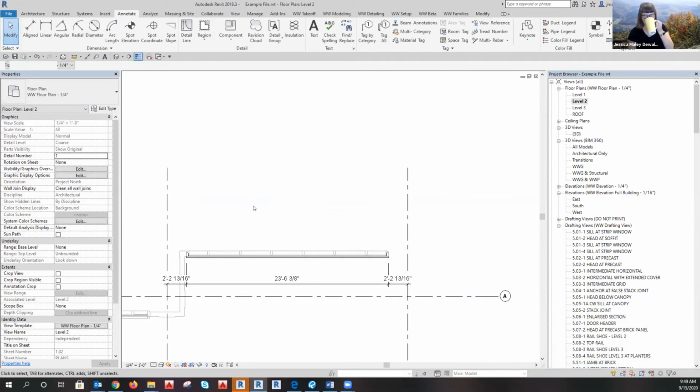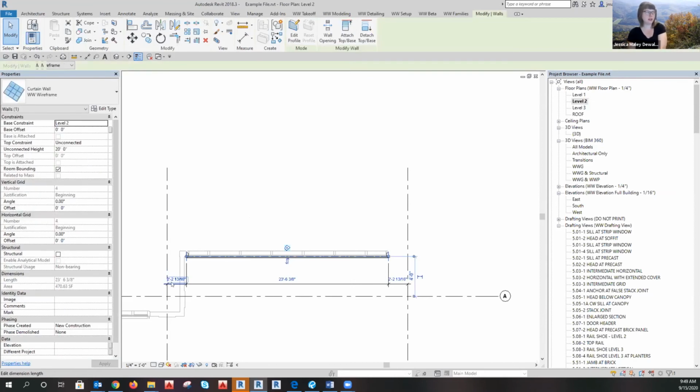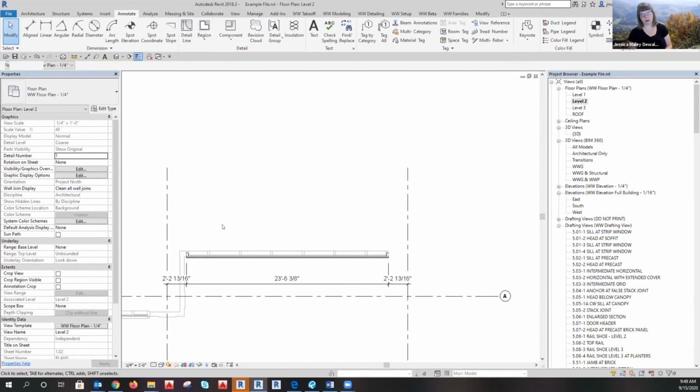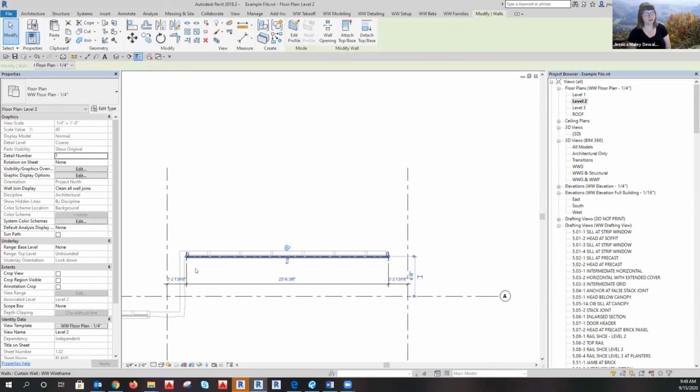So it doesn't matter where it is positioned on the back and forward, right? Right now. So that's why we're locking the end dimension after we change it, to keep it from just moving back and forward. Presumably, I would have my architectural set open, and I would know that I'm supposed to have this distance to the DP from the grid line. Or if that dimension was missing in the architectural set, make my best guess and document it somewhere to send an RFI to the architect.